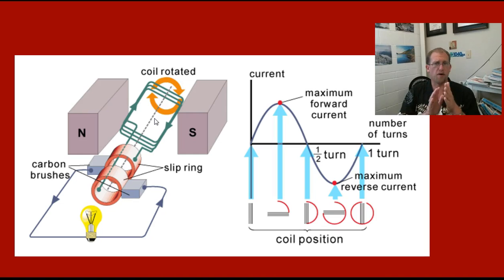The electrons are going to vibrate, going back and forth. And the number of oscillations per second, the frequency of the electrical power being produced, has to do with how many rotations per minute the armature is making between the magnets. Okay, and then you would see that this side of the armature is always attached to this ring, is always brushing this ring, right?